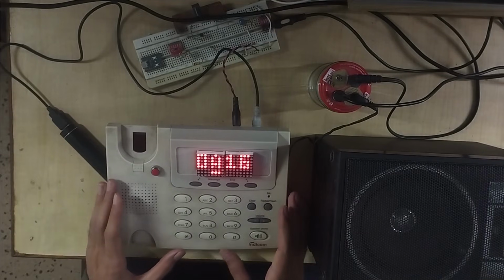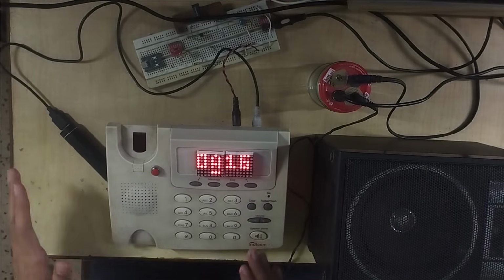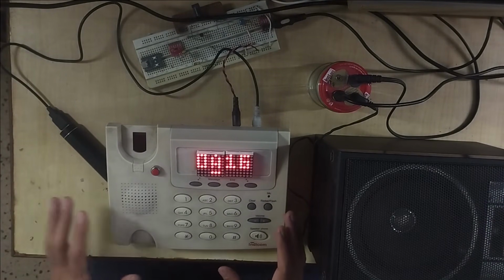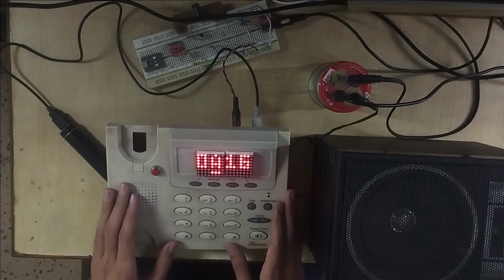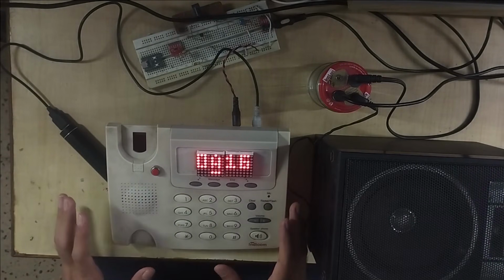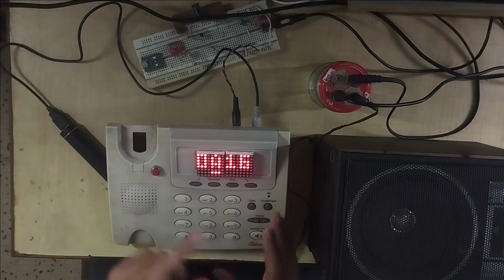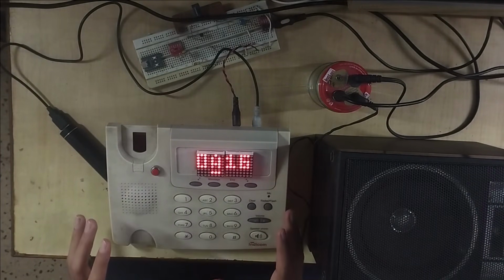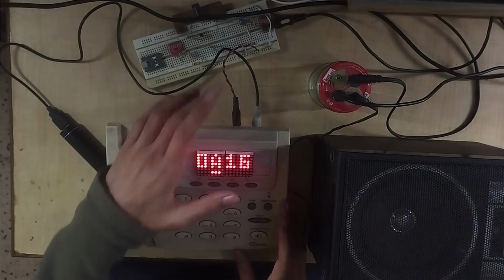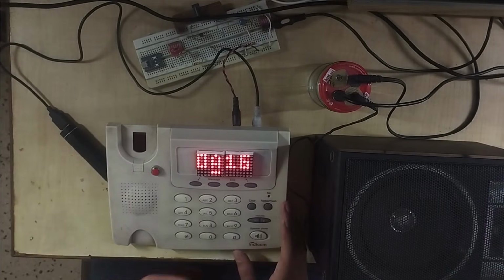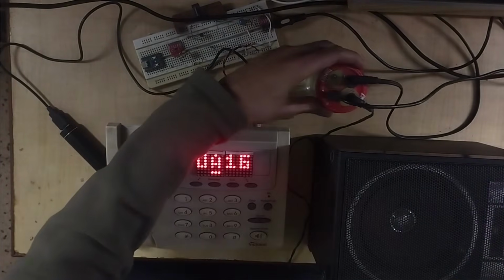All you need to do is power it up using 5 volts from any 5 volt supply, either a battery bank or a phone charger or something like that. And the audio out for the drum machine needs to go to an amplifier. In my case, since the drum machine and my amplifier don't have a volume control, I'm first taking the audio out to a breadboard where a voltage divider is reducing the volume, and then that is going to my DIY amplifier.